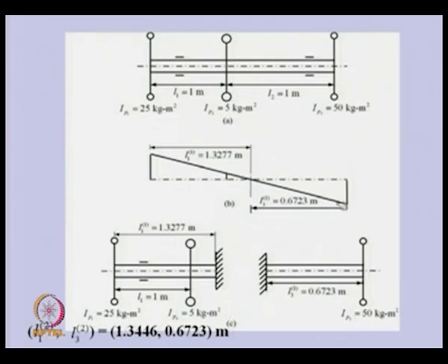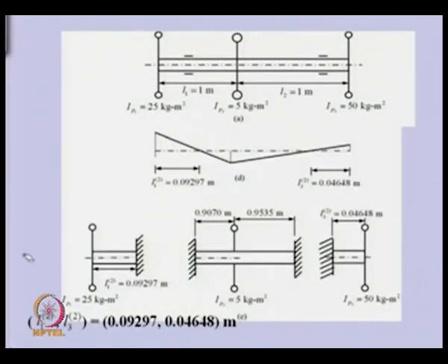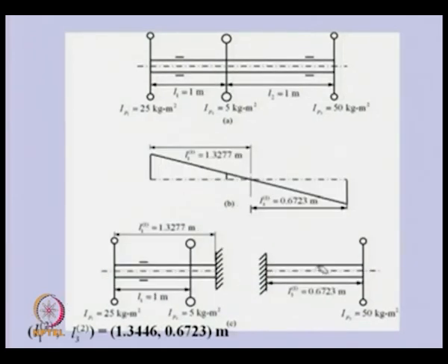If we take that, this will be a cantilever beam of this, and we can obtain the natural frequency corresponding to this length. That will give us the second natural frequency. So basically from the same solution we are getting both flexible natural frequencies, one from this and another from this.